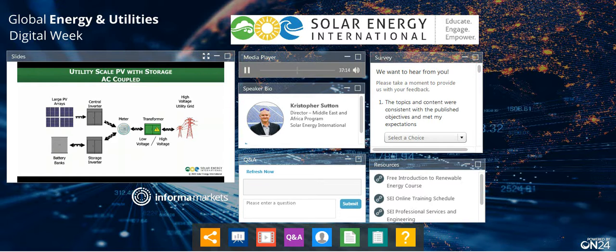So we can put battery and solar inverters in parallel if they're designed to work together. And what they'll do is they'll end up with a communication system to the utility that'll make decisions based on when to charge the batteries and when to discharge the batteries. And if a cloud comes over, we may push battery power out into the grid to keep it stable. And if the sun comes back out, we may push excess solar into the battery to recharge it. So we can take the solar curves and the outputs of the PV production and change it by using the battery to our advantage.